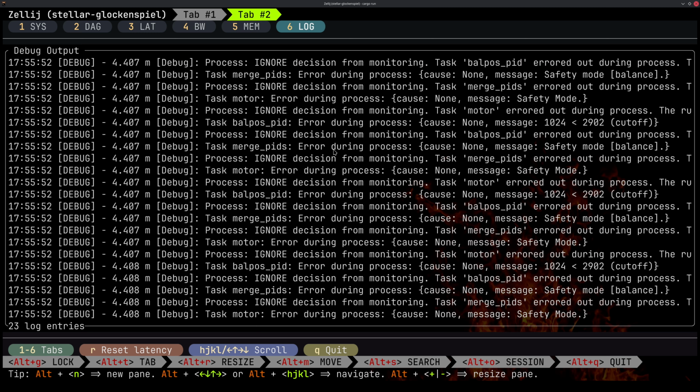And you can see on the last tab, we have structured logging with Copper. It means that we have a way to log only data out of your traces. Those debug logs are really text logs, but when you use them with Copper, you don't actually log text. You log only a reference to the message and the content of the parameters to rebuild those messages. So it's super optimized, so you can feel free to add those debug exclamation points in your code base, and that won't slow down your robot.